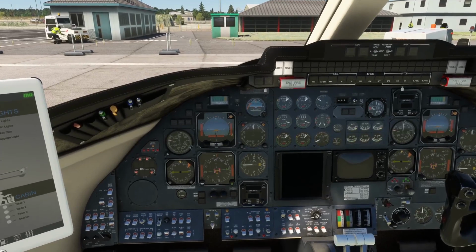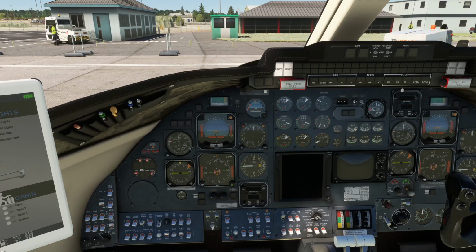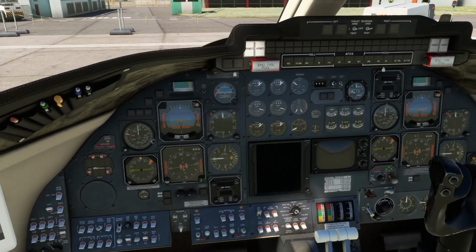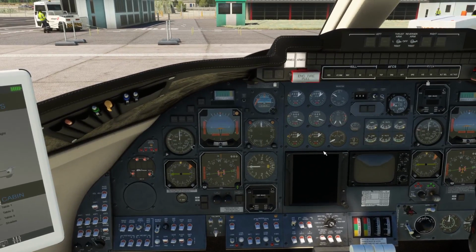There is significant redundancy in the electrical system. Each generator can provide all the electrical needs of the aircraft on its own. Likewise, each battery can provide all the electrical needs of the aircraft on its own, although for a limited time, and each inverter can provide all the AC electrical needs on its own as well. I mean, the inverters are solid state. They are not items that fail very often. And then, as I said in the intro, you've got the emergency battery if all else has failed.